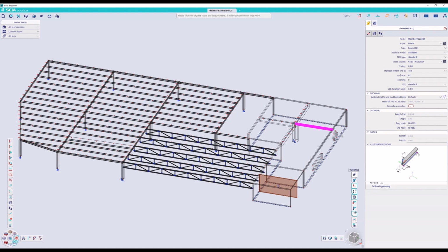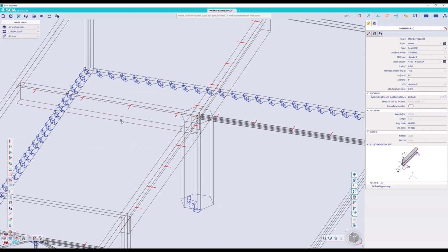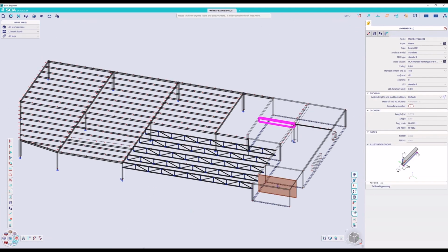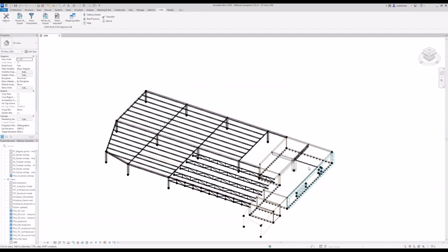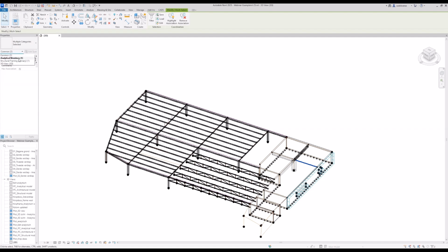This is also a property that is actually defined in the structural model of Revit. You will see based on the volumes that this is correctly taken into account and that other beams have the same setting too. If we take a look into the structural model in Revit, we will see that there is a property called justification Z, and that for this property the top is selected as well. Keep in mind that this eccentricity has an influence in SCIA Engineer and on the analysis results.